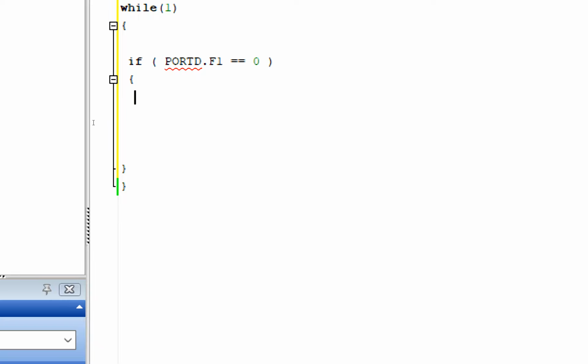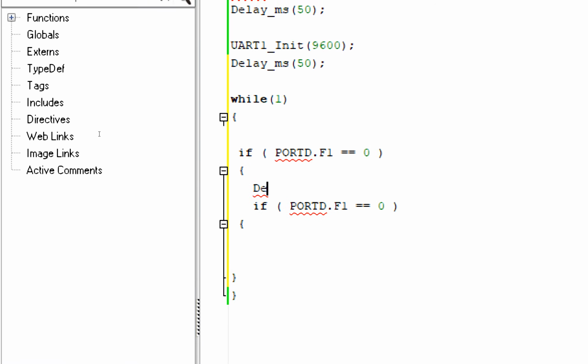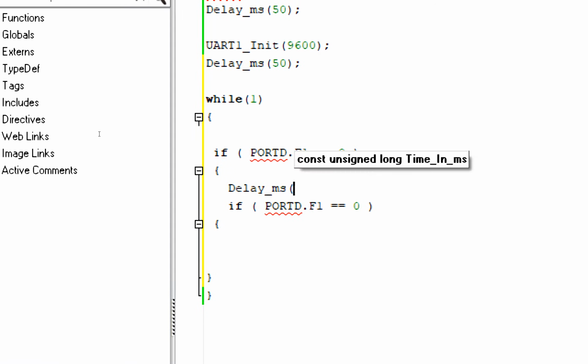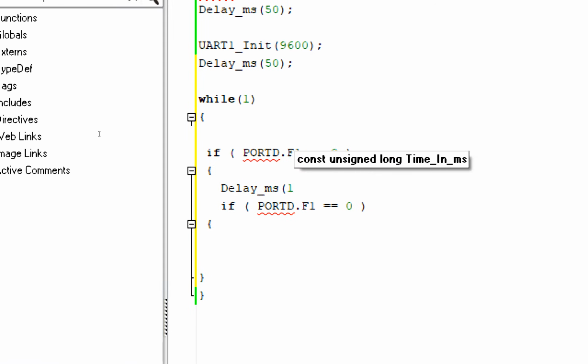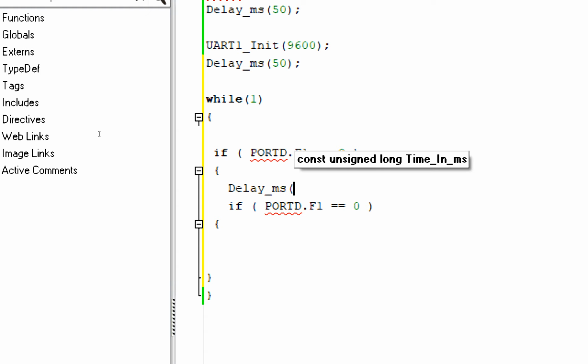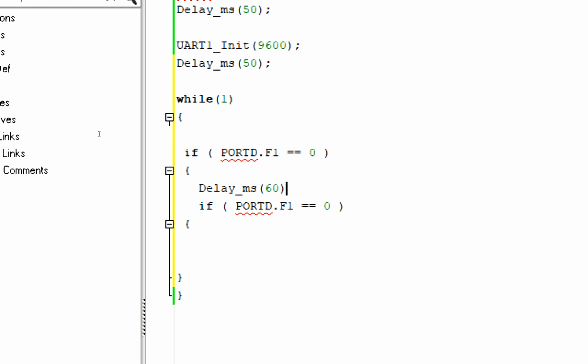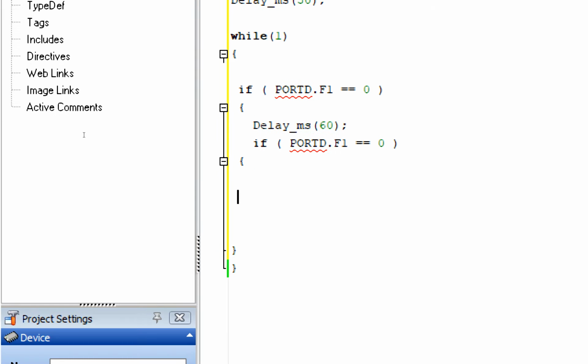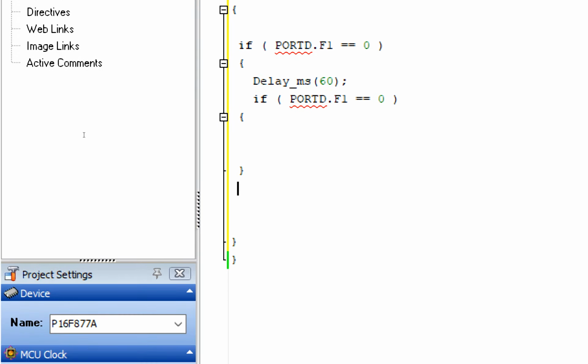So what we do is we add a delay again. Now if the sound is detected and the sound is still there, like a whistle, for more than, I say, 60 milliseconds. Although it is very little, we will start with this, and we will change this in case needed. Then consider it a whistle, that the whistle is detected.